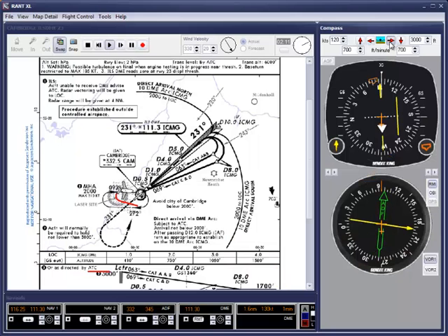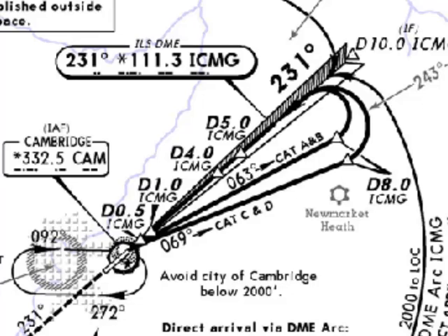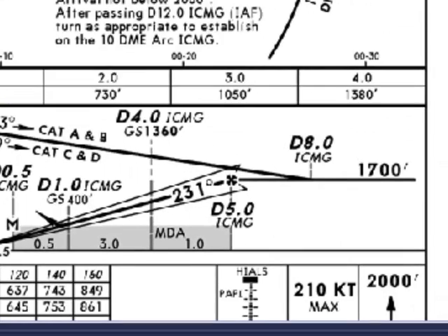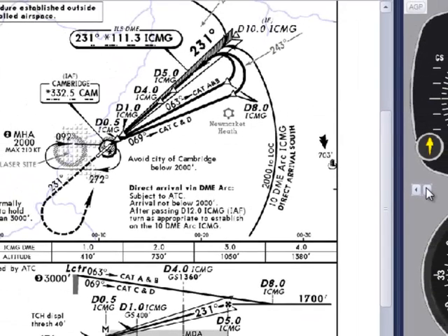Before I let the aircraft run, I'll just sort out a few things. The ILS frequency is 111.3. Next, checking with the Jeppesen plate, I see that the outbound course for a Cat A aircraft is 063 degrees, and that when established on that, I can descend to 1700 feet. The turn inbound is at 8 miles on the DME, and the inbound QDM is 231 degrees.